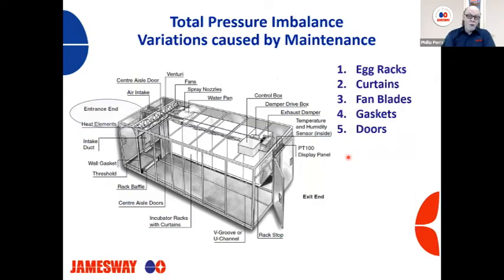Again, we mentioned the doors, that they're latching properly. A good way, I'm sure you know, is to step inside, turn the lights off, and see if you can see any light around the door and around the gaskets, which would show air leakage, either going out through the exit or through your entrance. It'll draw air in through there.